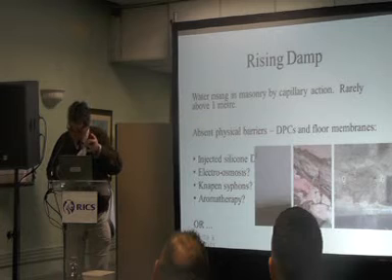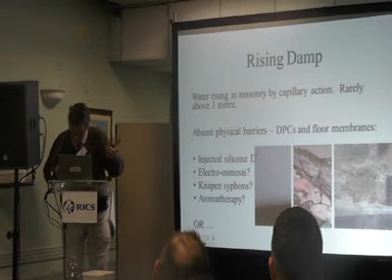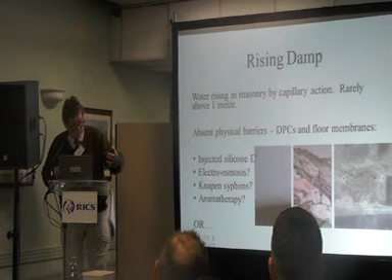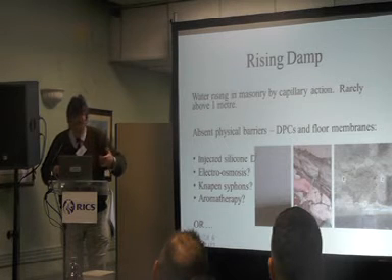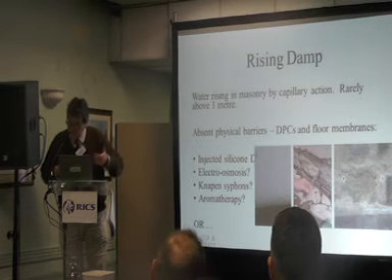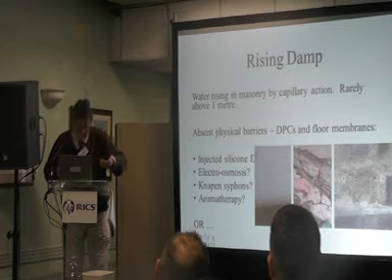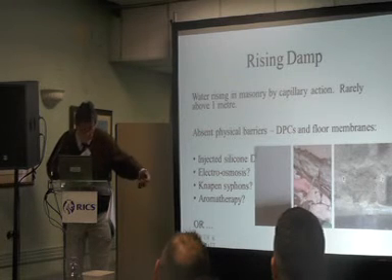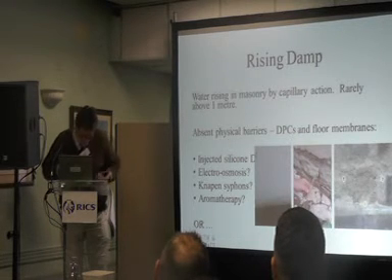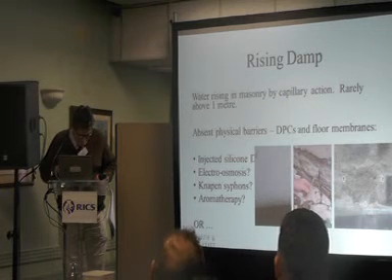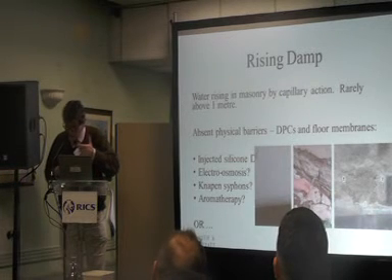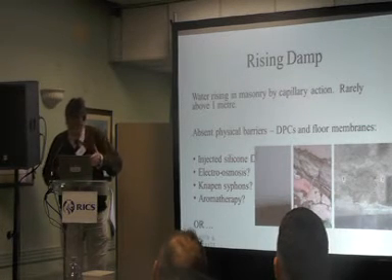For measuring damp it's rubbish. It's as good at detecting damp as this one. So this makes a nice squeaky noise. The damper it is, the higher the squeak. I love taking this round houses with clients because I poke it in the wall. Ooh, you got a bit of, ooh, ooh. But it's not reliable, and I'm going to have to come off here to show you why.